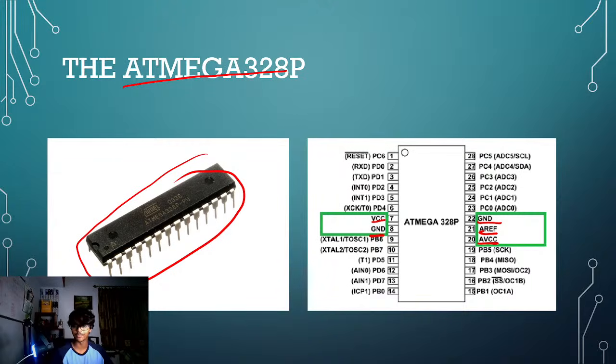It can be 4.7 volt, and these are used when there are real world sensors, like a temperature sensor, for example. It can't really convey information in the form of digital signals, right? So if it measures a certain temperature, it has to convey that temperature measurement in the form of a voltage, and that voltage is not going to be either 0 or 5. It's going to be something in between for it to convey what it measured, right?